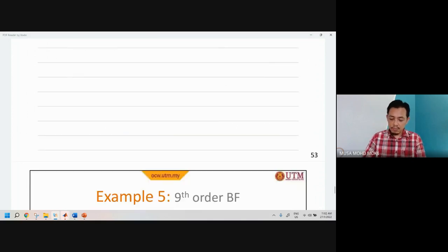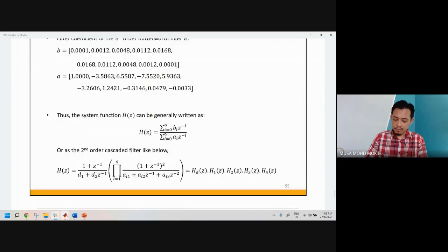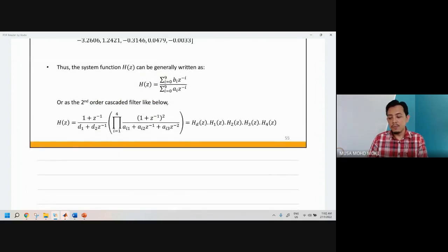If we look at this realization, assuming we have 2 second order filters, let's say only H1 and H2. The first one is second order, the second one is second order, and the operation is multiplication. Because the operation is multiplication, of course you will get fourth order. It's just 2 multiplied by 2. So the answer is yes, you will get fourth order.